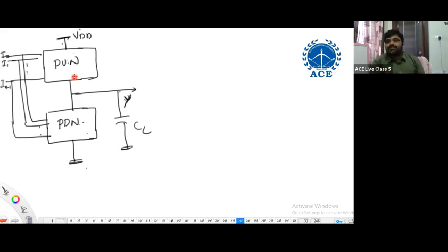This is the concept. In CMOS, switches are constructed dual in nature and using complementary MOSFETs. So dual, complementing each switch gives a complementary switch or complementary function. Then when one is on, the other should be off. Yes, we achieve the expected result of eliminating static power.